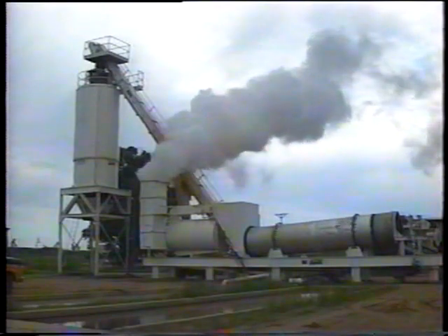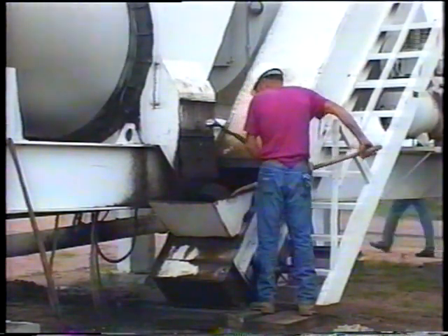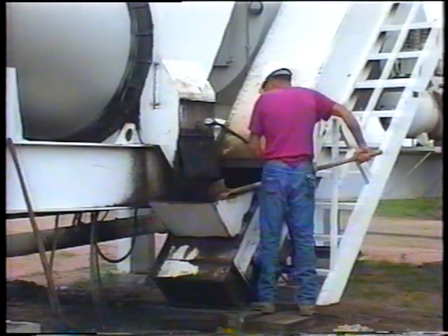There are several mix defects that can occur at the plant, especially a plant as schizophrenic as we ask this one to be. Blue smoke indicates that the mix is too hot, way too hot. If a haul truck delivers mix to the job that's still smoking blue, just imagine how hot it was at the plant. Check the temperature immediately and reject it if it's out of spec. Asphalt this hot is probably burned, so its chemical properties are altered, meaning its binding ability is lost.